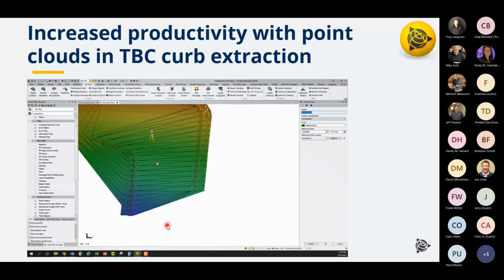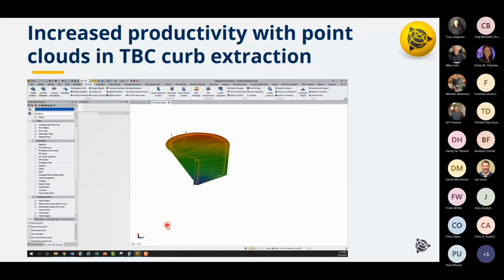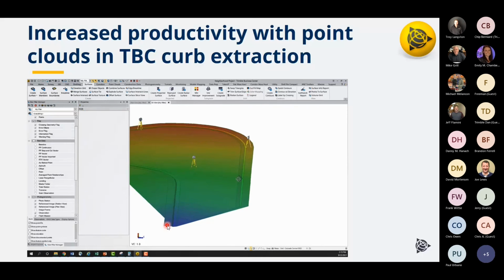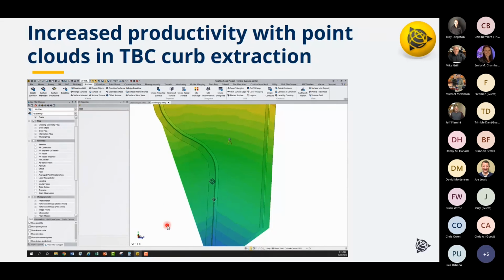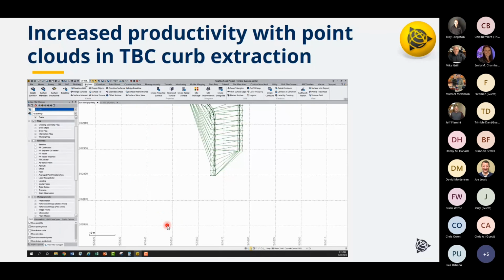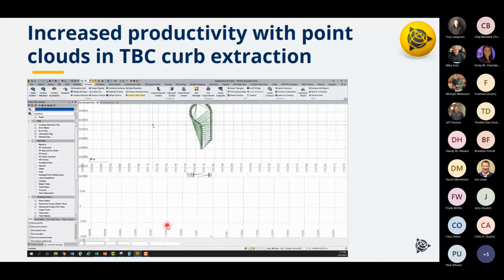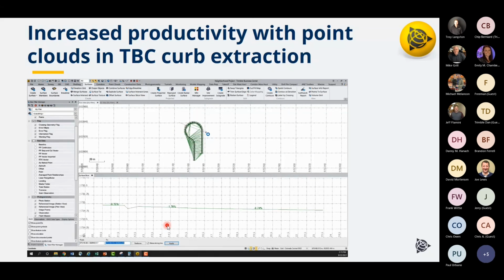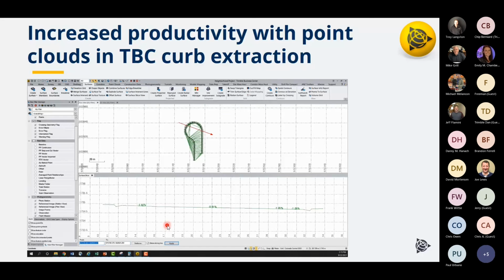And we have lots of surface tools. I could clean those up, but the big thing here is now we can see the shape of that cul-de-sac, right? Based on the line work that we extracted out of that. Okay, so here I did a surface slice, and just to view how that curb and gutter looks, and this is all done right in Business Center, so I'm not exporting anything out.